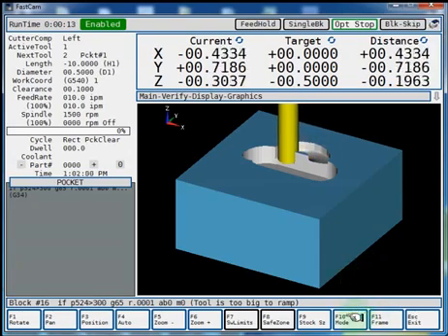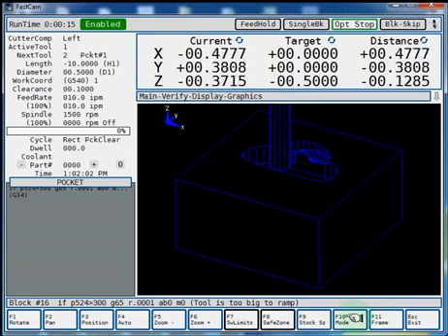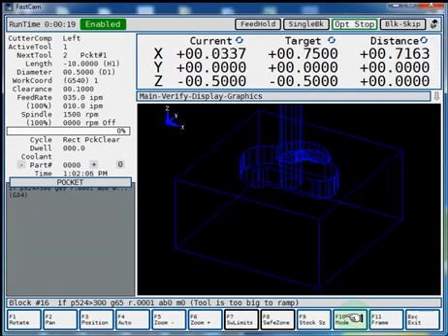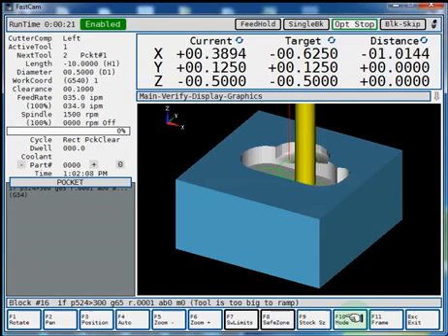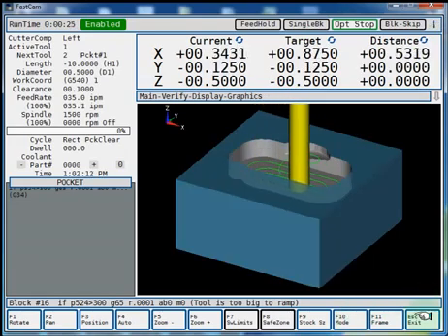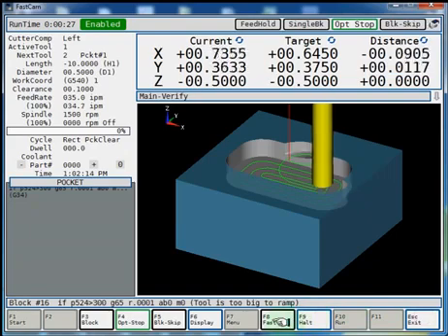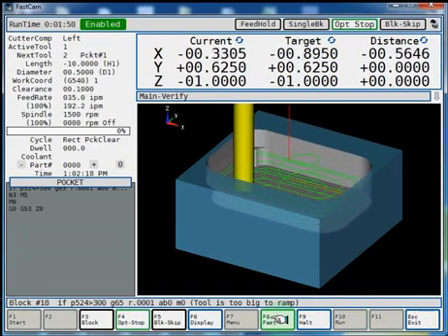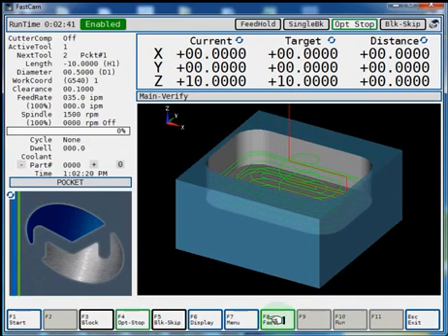And you also have a few different modes. If you click on F10, semi-transparent, a wireframe, solid model with your tool path. Hit escape one more time. F8 fast will come up so you can dry run it through your program. It shows your complete program, gives a cycle time estimate. And that concludes our program. Thank you.